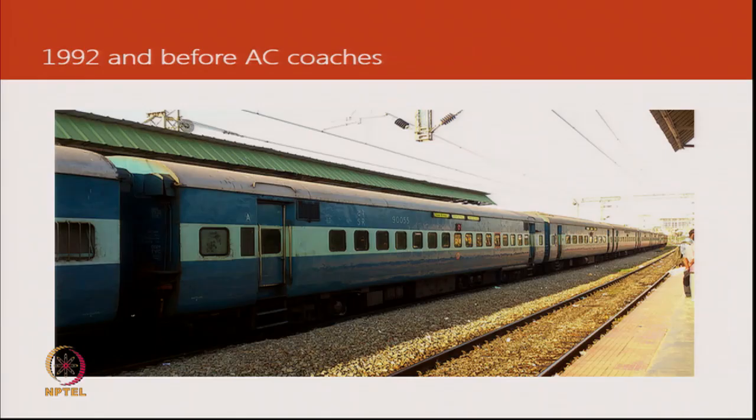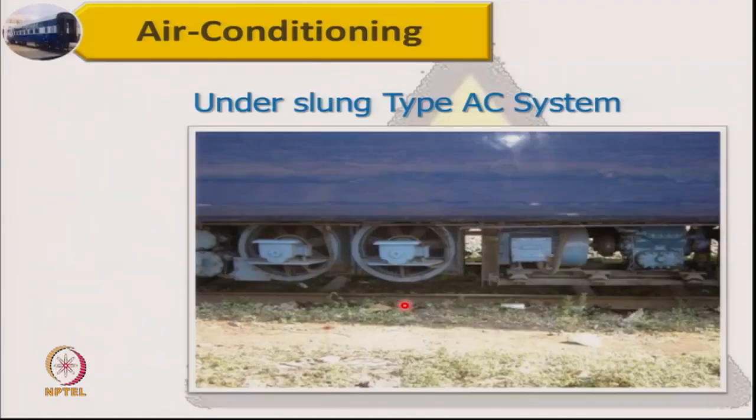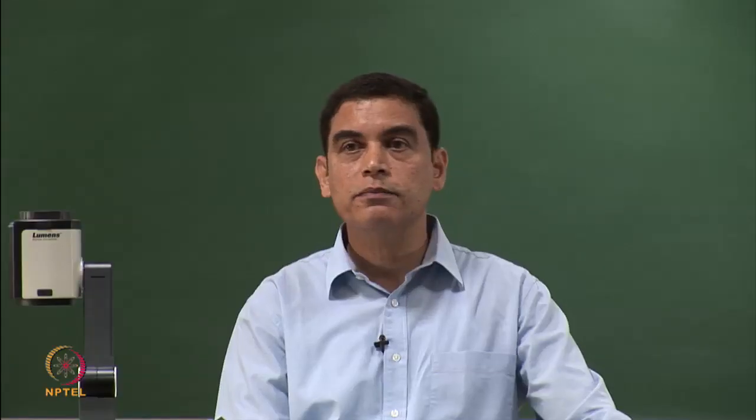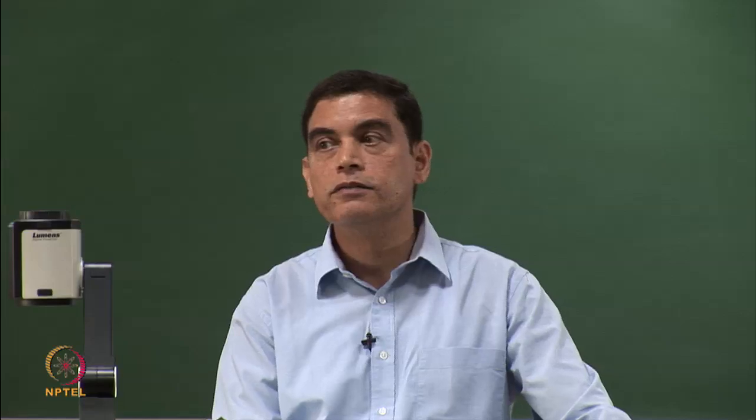So this is a view of a train, and if you look at the area where the condensing unit is, this part is not so clear. So the next slide we can see it a little more clearly. There are 2 axial flow fans, and then there is a semi-hermetic compressor which is driven by an electric motor. This is very bulky equipment which was using R12 as refrigerant. It was imported, and then a part of it was indigenized. Stone India was the only supplier for this equipment.